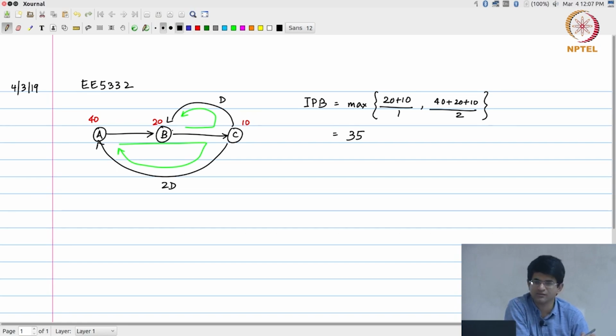B has an input coming from A, same story, there is nothing available on its input. B also has another input coming from C which has a token on it, but that does not help, I need tokens on both its inputs. And A on the other hand has 2 tokens ready, 2 initial conditions. It is like, you know, the C of -1 and C of -2, both data are available, I can use them in order to compute the A of 0 and A of 1.